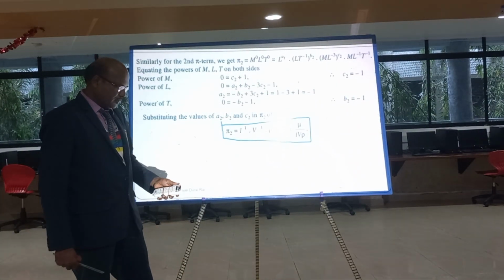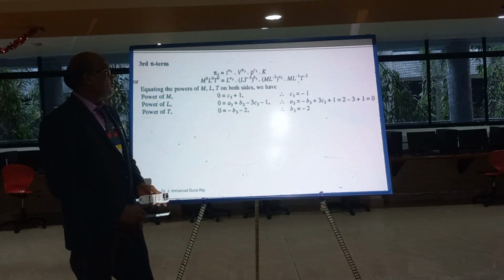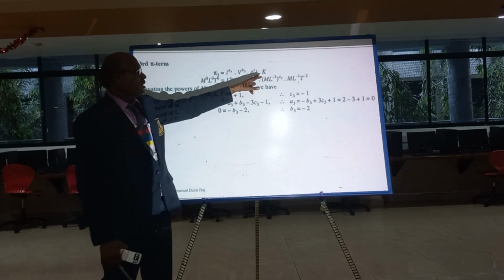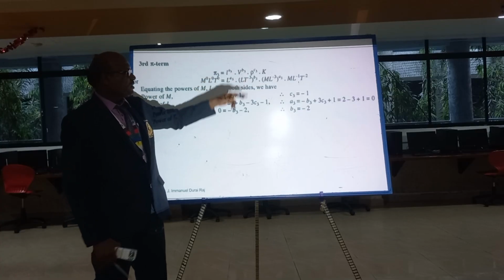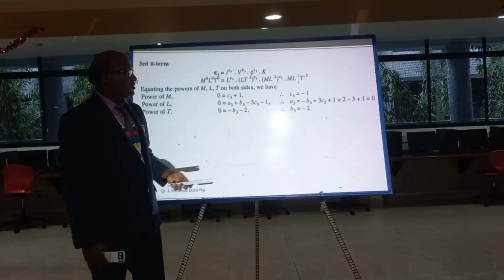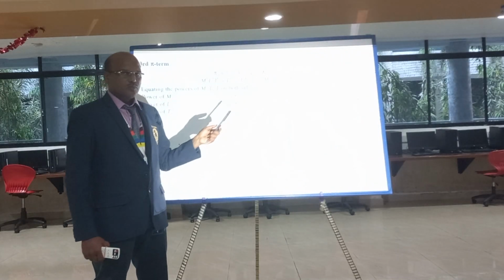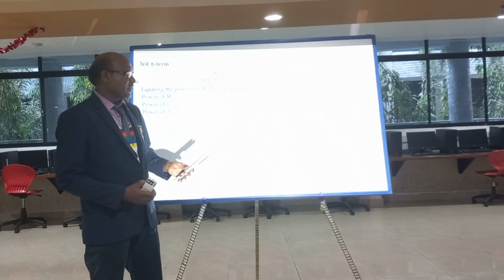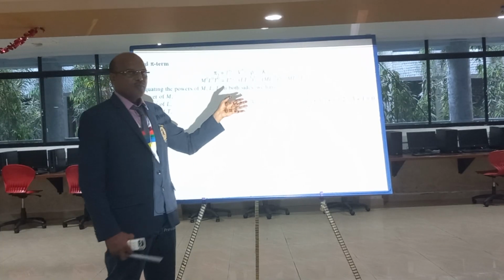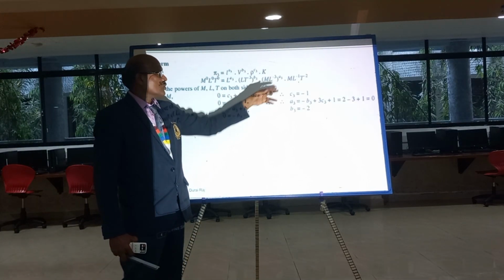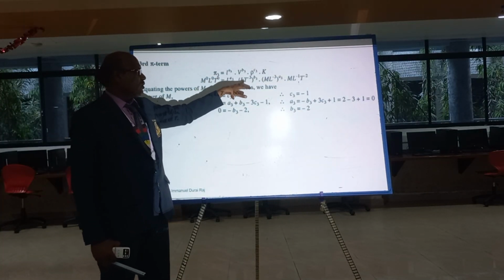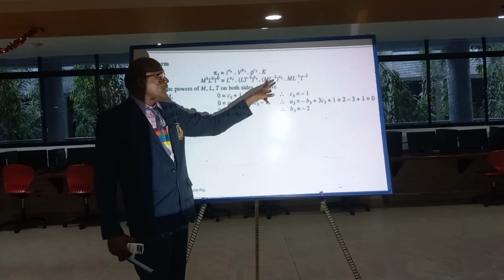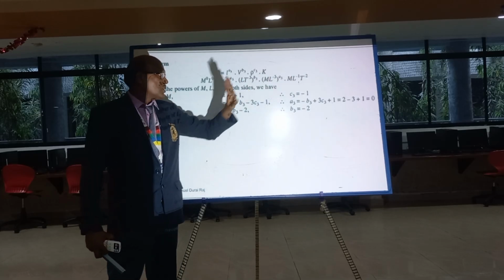Similarly, go for the phi 3 term. With the phi 3 term, the remaining variable is bulk modulus. The repeating variables are L power A3, V power B3, and density power C3, and bulk modulus. Bulk modulus is Newton per meter square. If you know Newton and meter square, you can write it as M L T power minus 2 divided by L square. So you get this equation. As before, one is geometry, one is flow, one is fluid property, and your last term.